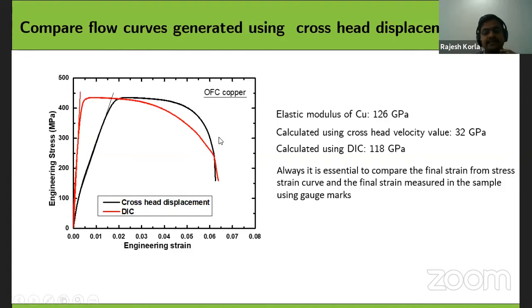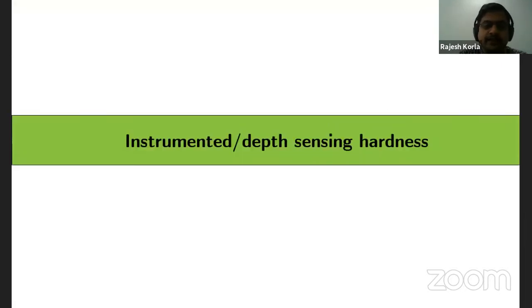So for every tensile experiment, it is important to calculate the displacement from the mechanical test machine and the displacement from the sample after the fracture, and see whether these two are comparable or not before making any validated conclusions. Okay, now I'm going to instrumented depth sensing hardness.